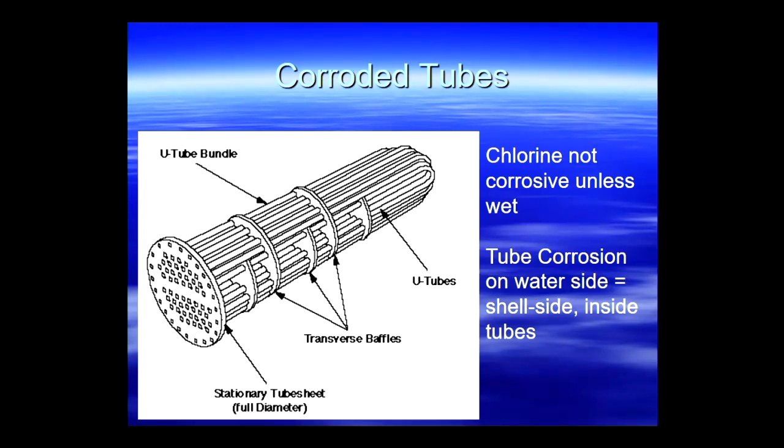There's buckets of salt in the air. And if they'd lost control of pH and their dosing, then they're basically circulating seawater through the system, which would be eating these tubes out quite quickly, which is exactly what was happening. I said, well, why don't we fix the cooling water? Oh, no, couldn't do that. That's a huge job.